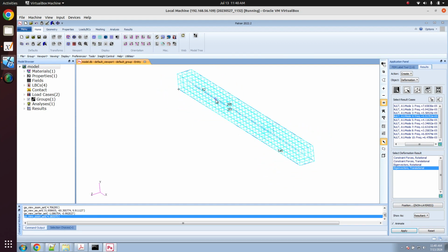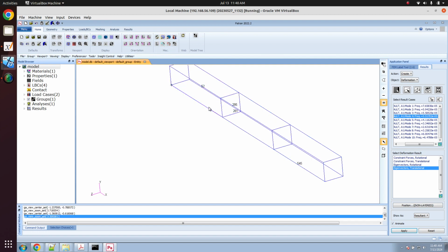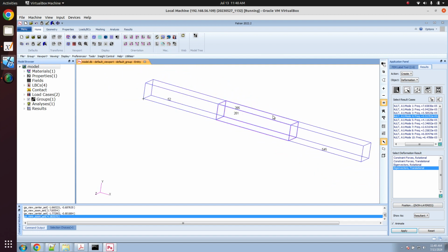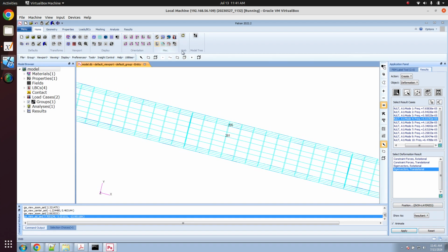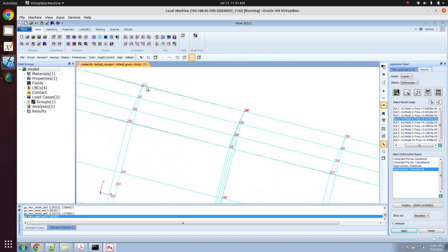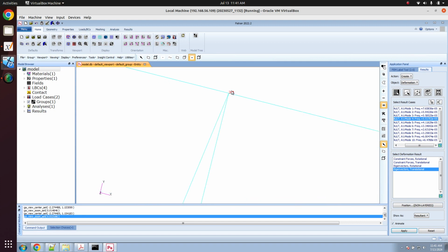In this case, when we meshed this geometry, let me show you the geometry. The geometry was actually 3 separate boxes, if you will, box 1, box 2, and box 3. So we meshed this, but if you look carefully at the interface, here you have node 208, 256, but if you look carefully here, there are 2 nodes that are overlapping, and that's why you cannot read the label. There are 2 numbers overlapping each other. There are 2 nodes here.